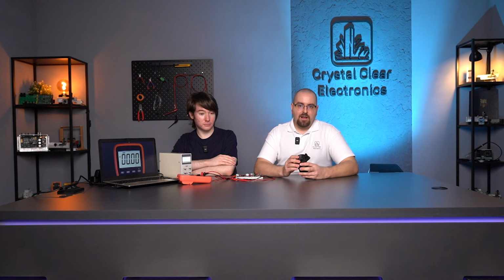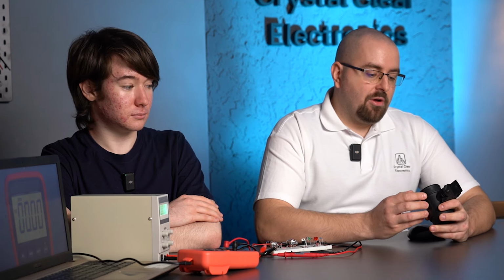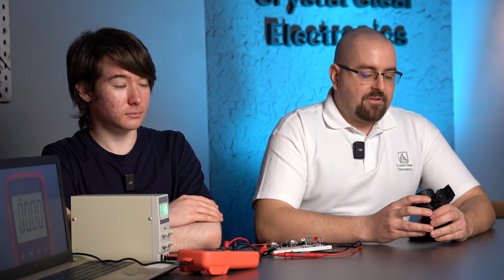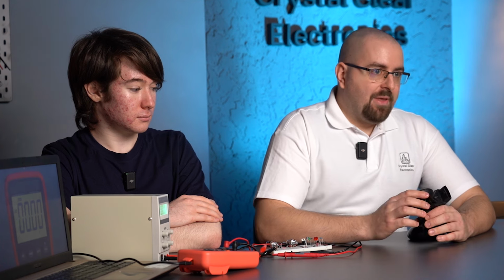It has a metal wire through which a constant current is driven by electronics. This metal wire is positioned in the tube here so that the air sucked in by the petrol engine can flow past it and cool the wire. Because the flow of current heats this wire, if the air flows past it very quickly, it will have a lower temperature because it cools it, whereas if the air flows slowly, it will be warmer. It is good because the electronics can determine how much air can flow through it by measuring the resistance of the wire.